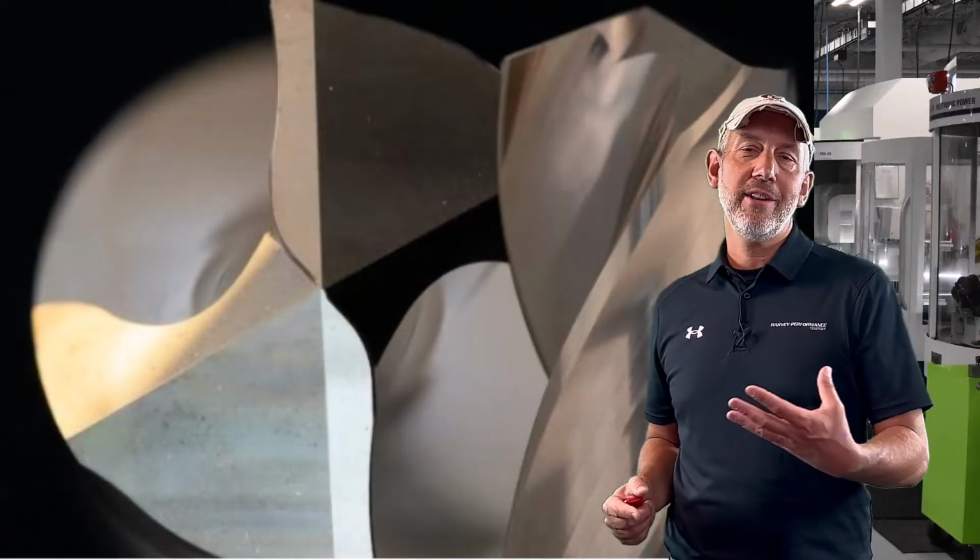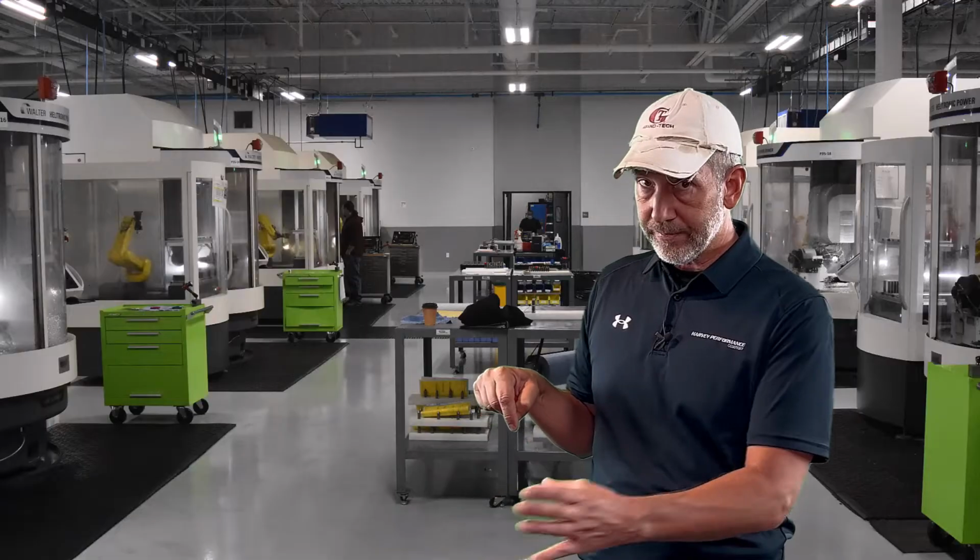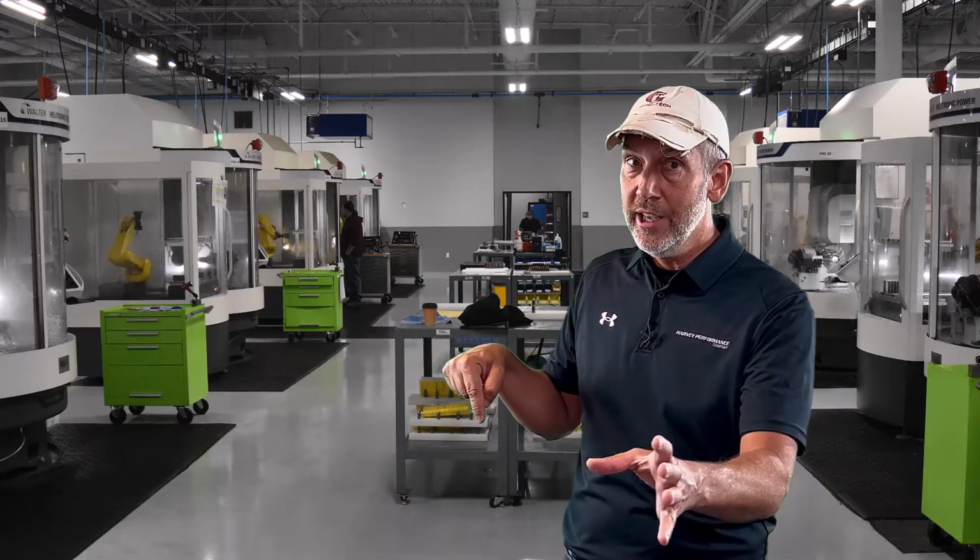Let's talk about spotting. When a drill starts, believe it or not, we design drills to self-center themselves. The point geometry on there is to self-center. How much? Usually up to 12 times D, you can run a drill without a spotting tool and it'll self-center itself. That being said, it might not give you the hole quality you're actually looking for. It might just walk a little bit at entry. So I'm telling you, can you use a drill up to 12 times D without spotting? Yes, you can. The geometry is designed to self-center it.